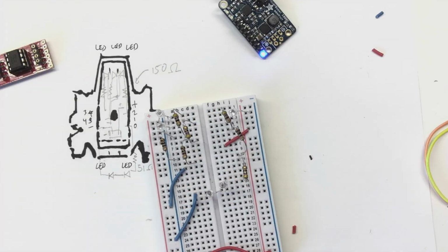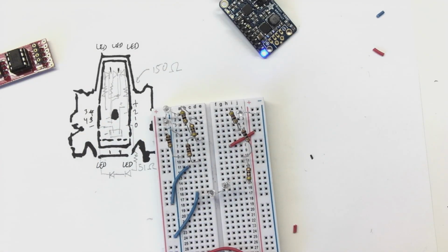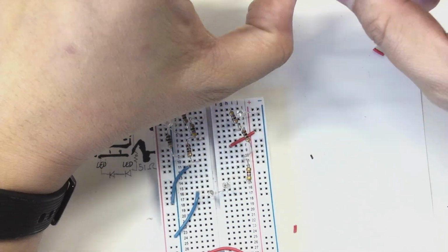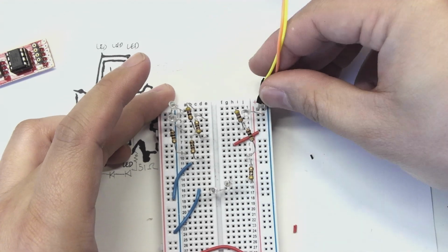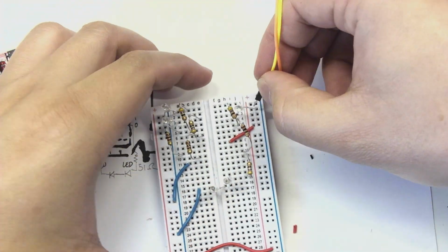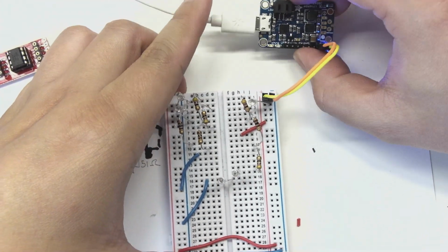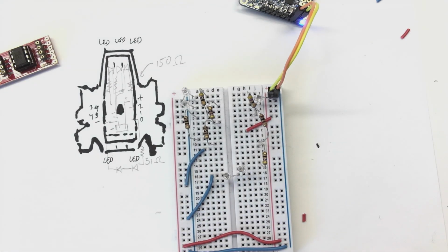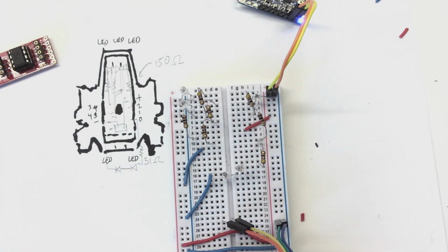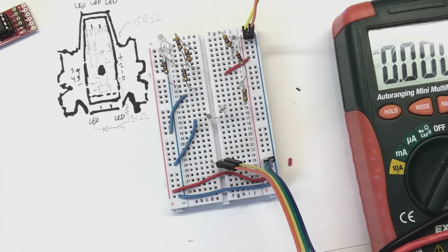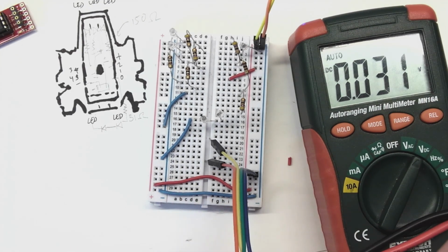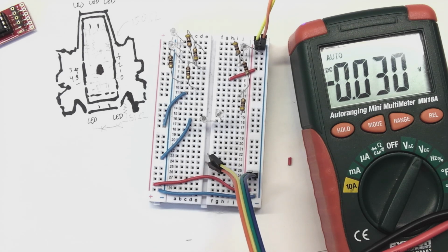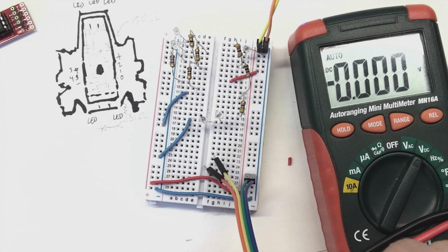To test the circuit, I plugged in a PowerBoost 500C, and then connected the 5V and ground connections to the positive and negative rails on the breadboard. Once I plug in the chip, I should be able to see whether or not the program and the circuit works. I used a multimeter to make sure that the 5V connection had the correct polarity. Since there's no diode protecting the chip from what's called reverse current, I needed to make absolutely sure that it was 5.1 volts in the correct direction. Finally, I pulled the chip off of the programmer and then plugged it in.